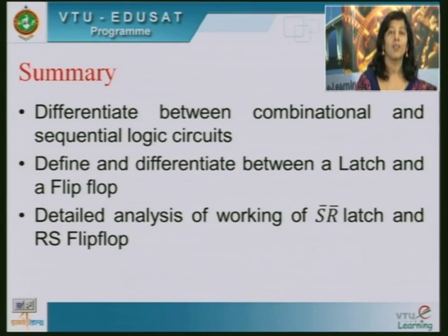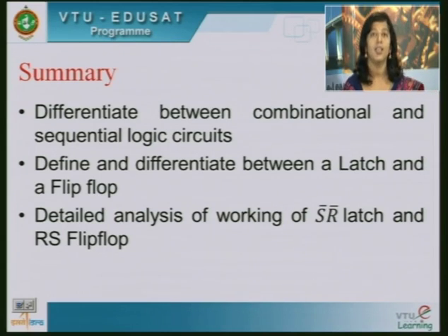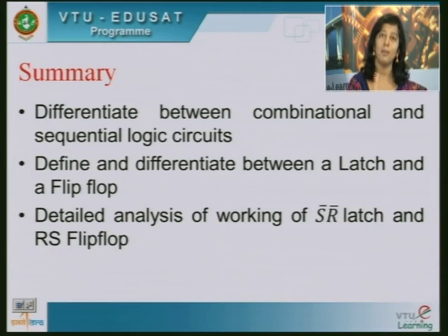So, in summary, what we learnt throughout this chapter, this is all you have in your syllabus for latches and flip flops. We learned to differentiate between combinational and sequential logic circuits. Combinational doesn't need a master clock. Present outputs depend only on present inputs and there is no need of clock. In sequential, a clock is needed, memory is needed, and present output depends on present as well as previous inputs and outputs. So, memory is there in sequential, no memory in combinational.